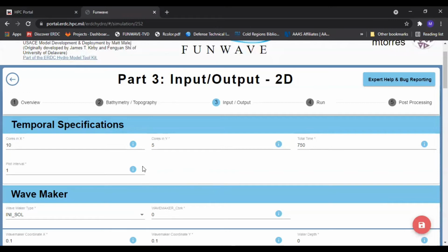Now, these global variables will have dimensions the size of your actual grid, so the size of those M globe and N globe variables. And the plot interval defines how often you want to plot that output, to write that file. If you wanted to have an output every 100 seconds of your simulation, let's say, you would put that here. So in this case, you would get 8 outputs from this simulation, including the initial output at 0 seconds, and the last output would be at 700 seconds, since it'll go up to the highest integer.